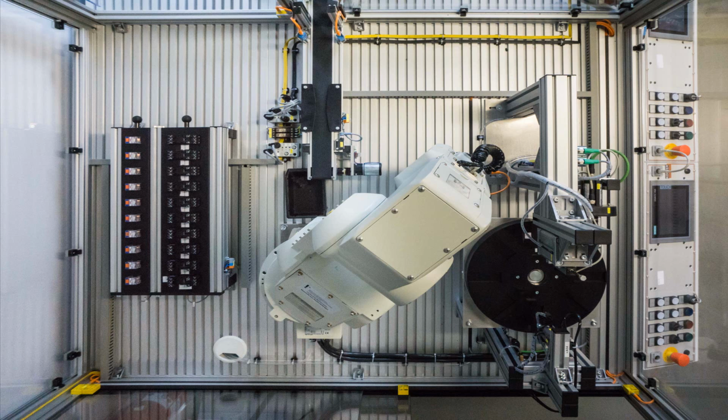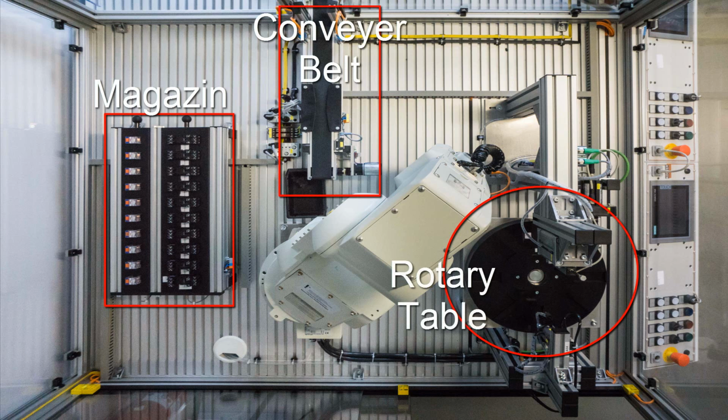Before we start to develop the robot control, we define different areas. First, the magazine, the conveyor belt, the rotary table, the home position, and the idle position. Later, we will use these areas to avoid collision. In the home position, the security system allows to open the door, and in the idle position, the robot does nothing.